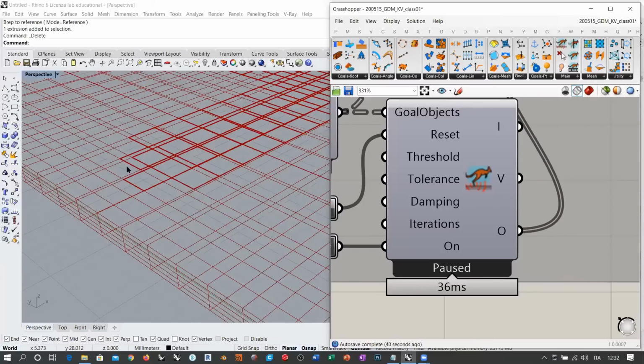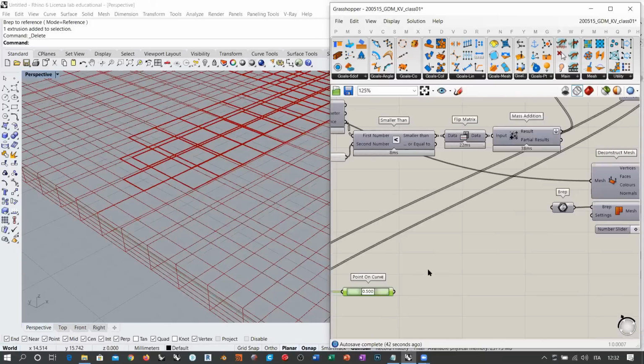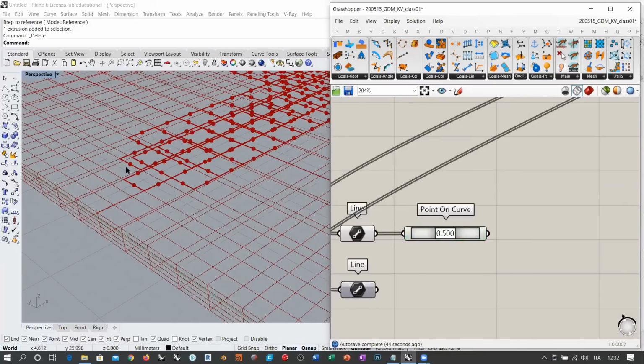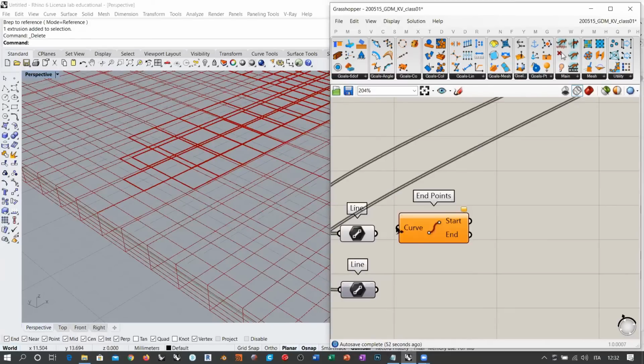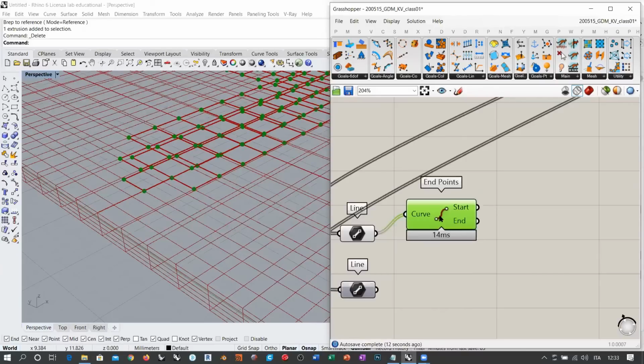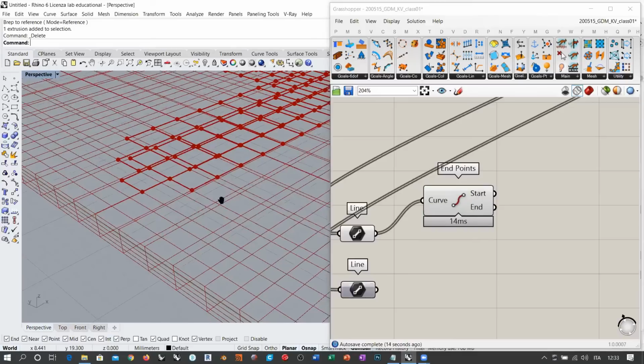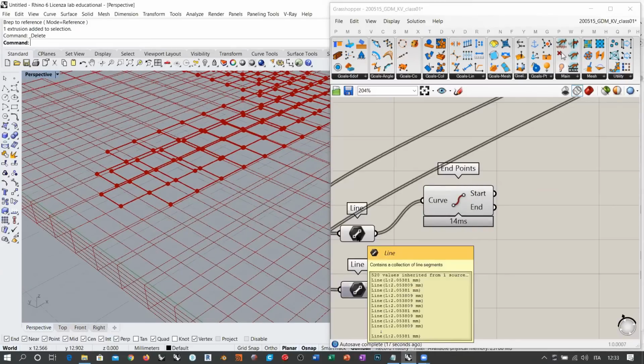Okay, so if I create a connection between the midpoints, this connection point cannot be taken into account by Kangaroo. So I must use the endpoints. If I create a vertical connection between these endpoints here, Kangaroo can take into account the elastic force that I bring to these new springs. How can I do this? Because now all these edges are grouped together into one single list.